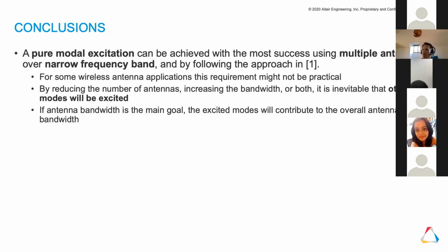However, obviously for many applications, this may not be practical. You may be limited to a single antenna or may have a requirement for a broader band. And then the approach that we investigated here comes into play. And the conclusion with respect to that is that although reducing to a single antenna and even working over wider bandwidths will result in unintended modes being excited, primarily with respect to bandwidth, these modes do seem to contribute positively to the overall bandwidth in that regard.